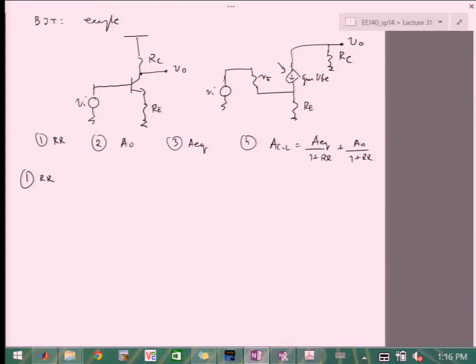The difficulty with that is that sometimes that's not the best place to cut the loop, and your analysis can get a little bit more involved if you always follow just that recipe. But really, there's no reason to just go and replace the dependent source, simply because return ratio is a unitless quantity. Wherever you cut the loop, you can essentially terminate and introduce a source. And so you should really be able to pick just a convenient place to do that.